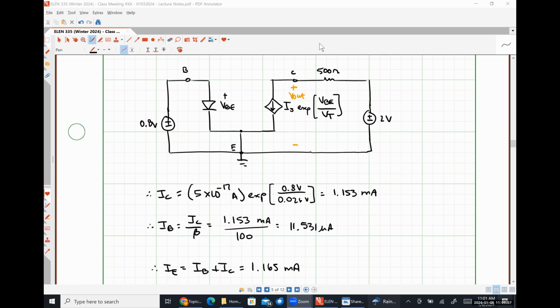And the small signal model's purpose is effectively saying, well, if I perturb this system by a small amount at its DC operating point, the tangent line of that exponential curve is going to be approximately linear.